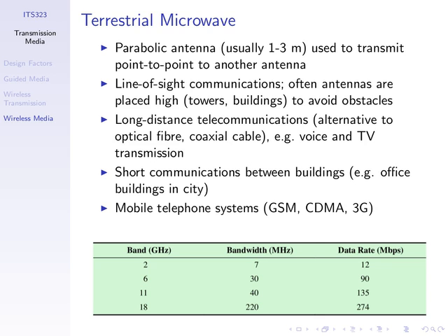So we have point-to-point links, and that's where we get line of sight. We refer to line of sight communications, meaning the transmitter and receiver are within the line of sight of each other. They can effectively see each other. And to avoid obstacles, because of the frequencies we use, they do not pass through obstacles such as buildings very well.